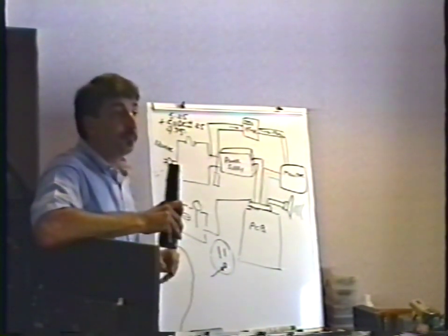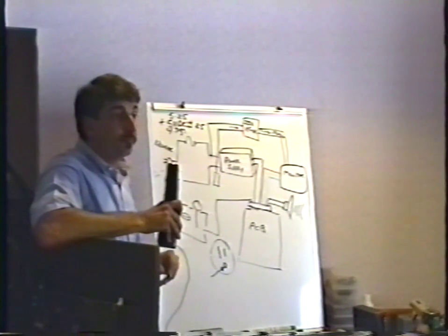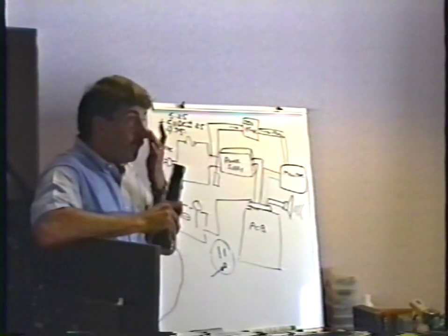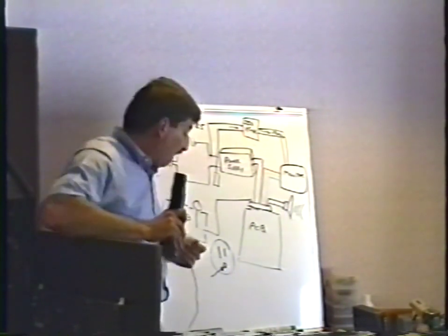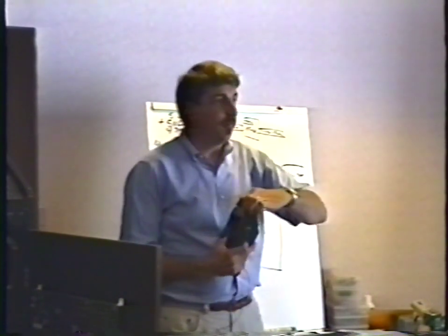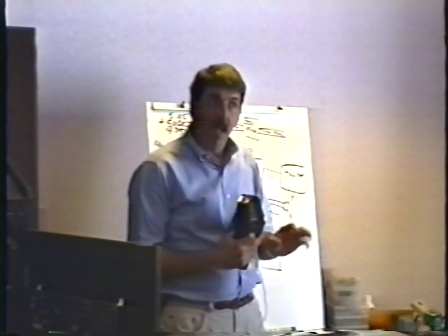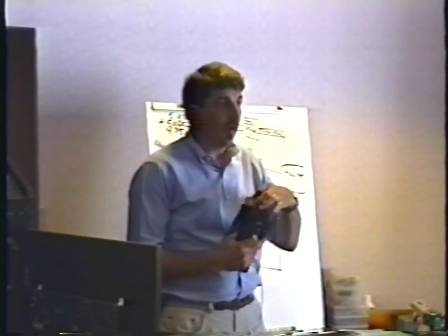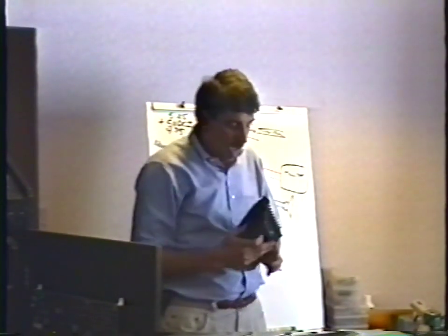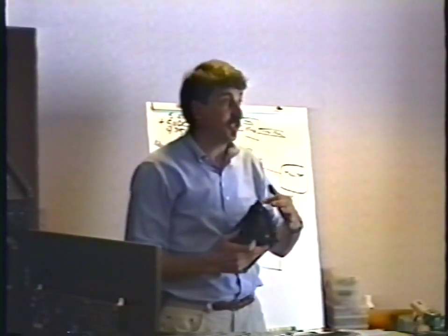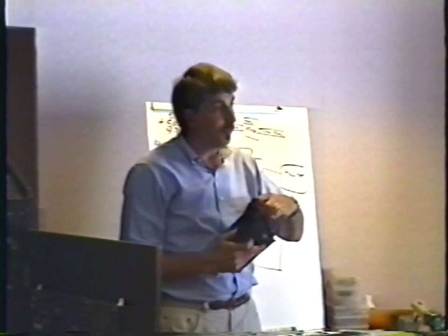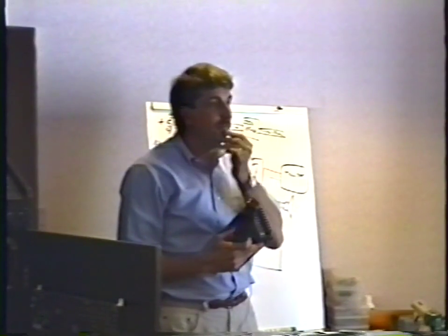Yeah, Ken. Is there any danger in adjusting that real fast too hard? You know, what if you just go way up high real fast, and you go way too high? Yeah, that's bad. Most power supplies are designed so that you cannot, even at maximum, go dangerously high. But I wouldn't trust a power supply at all. You never go, hey, let's see how high it goes. With the meter connected, never adjust this without a meter connected, by the way. But with the meter connected, just slowly bring it up or down. I wouldn't mess around too much.